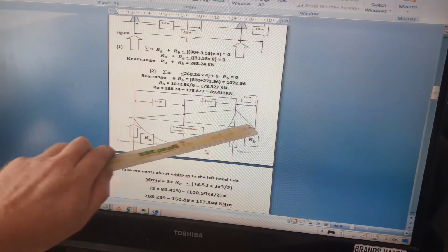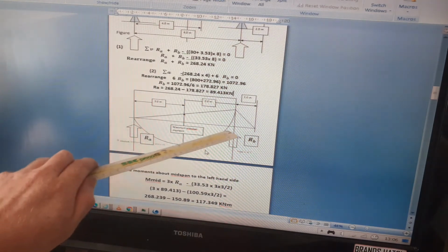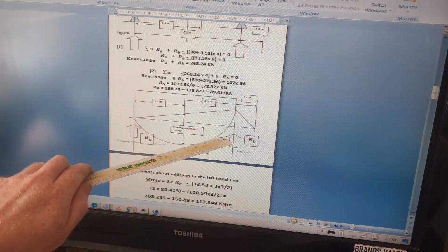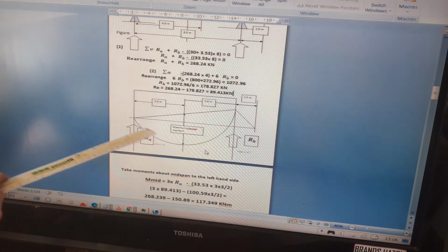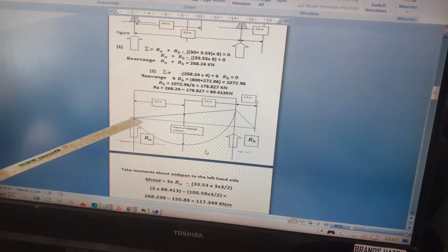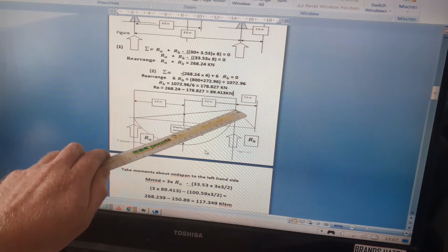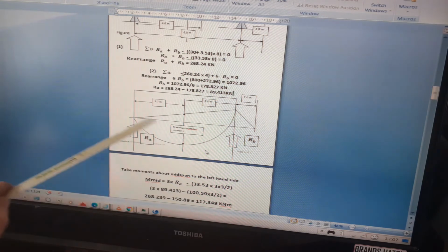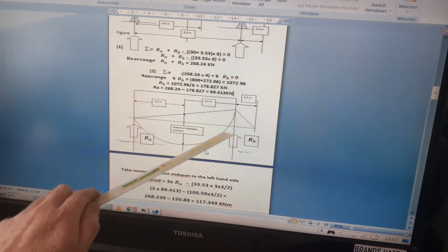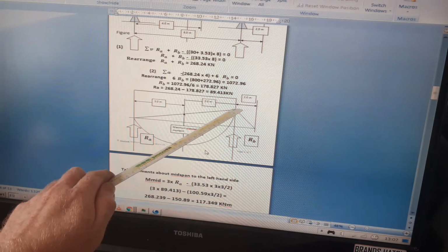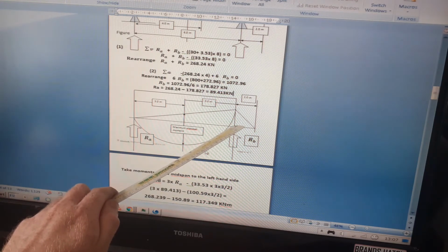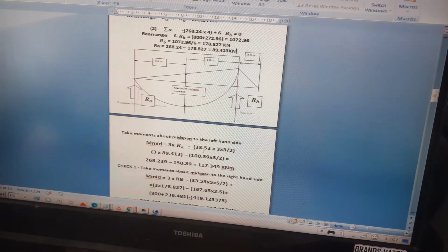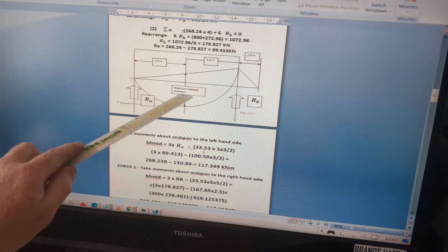We know that if this was simply supported without the cantilever, we just have WL squared divided by 8. So from experience, I think that the moment will look something like this, starting at 0 here, and then we have the fixed moment of the cantilever, which we calculated as 60 there, and between that point and that point it will be like simply supported. So we'll get a curving moment, but it will just finish at 60. Instead of finishing at 0 at RB, it will finish at 60 because that position is set.